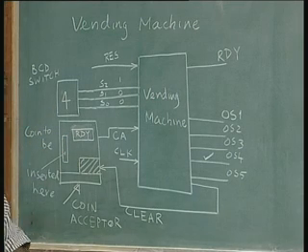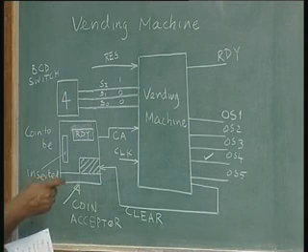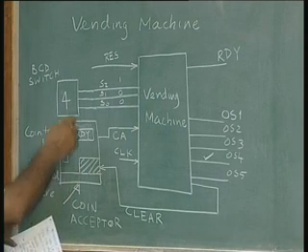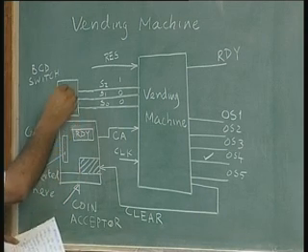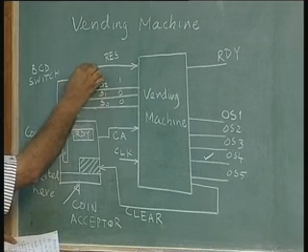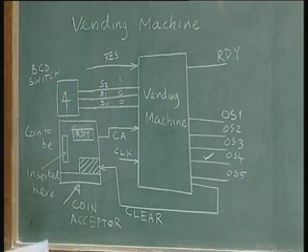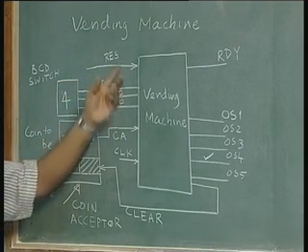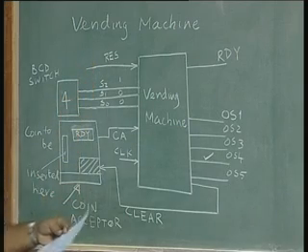And reset can be done in different ways. You can have a reset by a switch button. You might have seen this by a simple switch. I am not going to talk about this in microprocessor circuitry. You know how to do a reset, power on reset. We can have a simple RC circuit which can do this job.